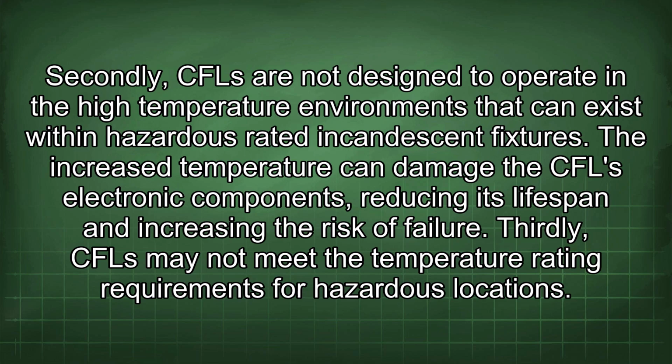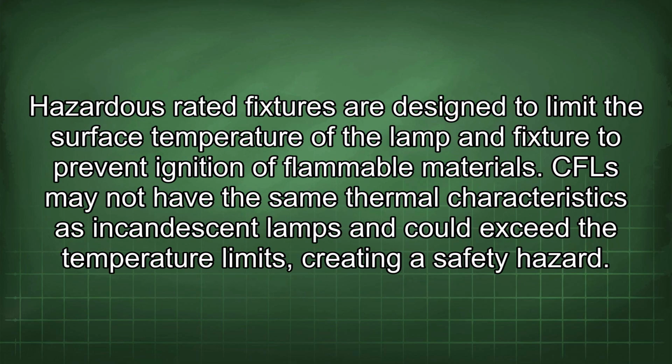Thirdly, CFLs may not meet the temperature rating requirements for hazardous locations. Hazardous rated fixtures are designed to limit the surface temperature of the lamp and fixture to prevent ignition of flammable materials. CFLs may not have the same thermal characteristics as incandescent lamps and could exceed the temperature limits, creating a safety hazard.